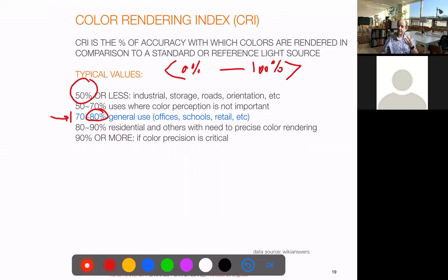And remember, our perception is logarithmic. As with sound, we need to increase the intensity of sound 10 times to perceive it as twice as big. So in terms of perception, 20% is not something we really feel as a big change, right? But 50 to 78 is a big change. Over that is for better. So usually in houses and places where we spend a long time, we try to go higher than 80. Around 80 is the reference. And in museums and so on, you'll try to go much more than 90.